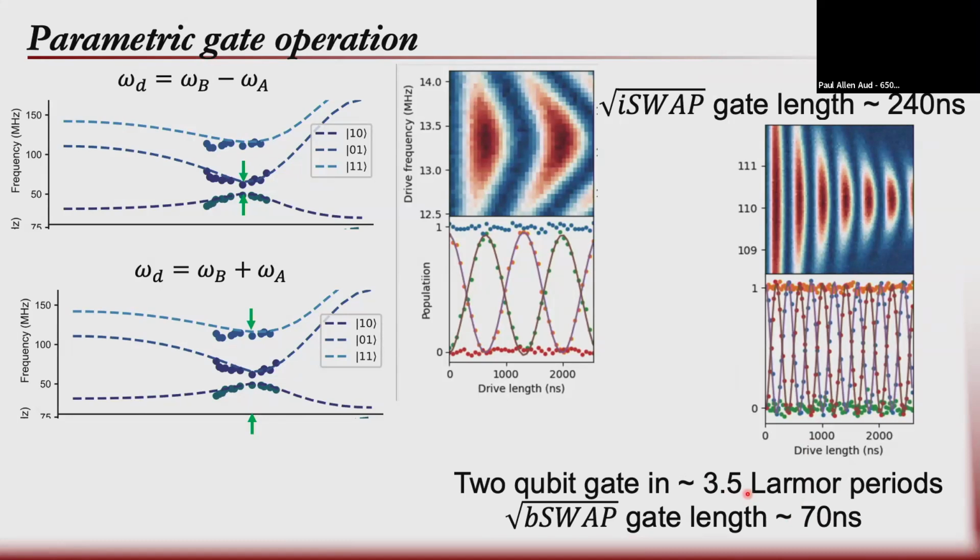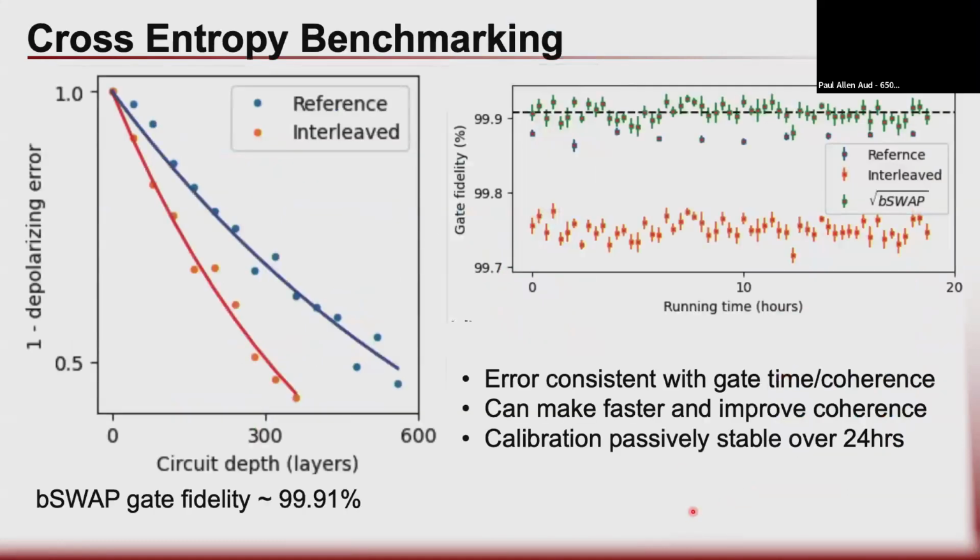Anyway, so we can use this as a qubit, and the gates are very good. They're like 3 nines for this one, and they're pretty stable. So you can make a good qubit out of it, and also a coupler, and that's pretty nice. Mazar will tell you about probably these ATS and CAT stuff, and that's also kind of like a fluxonium, but with a tunable EJ and used in a special way.